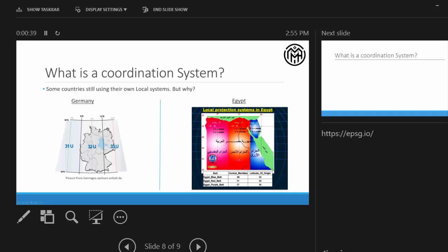Anyway, the 0 point is not my main focus right now. I focus on the origin point. And this origin point has false easting and false northing. And I know that my project was in Cairo, so that's somewhere here. So I have some imagination of where the survey point should lie.